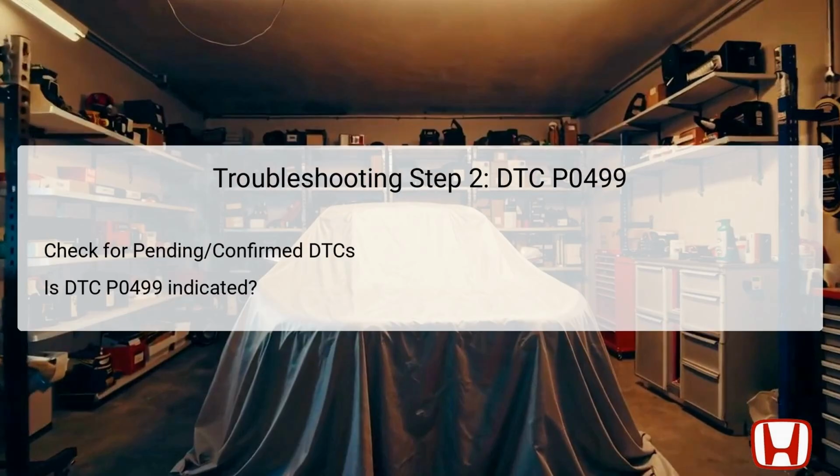In the second step, you will check for any pending or confirmed DTCs using the HDS. Pending DTCs are those that have been recorded but may not indicate a present fault, while confirmed DTCs represent issues actively affecting vehicle operation. It is essential to identify if DTC P0499 is still present at this stage, as it confirms the ongoing issue with the EVAP system.